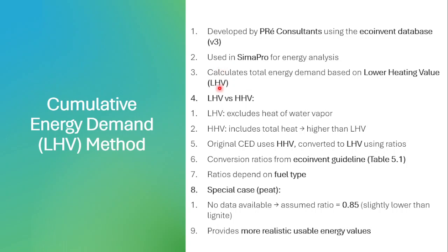This methodology calculates the total energy demand based on the lower heating value, LHV, because as you know, we have one methodology for the CED based on the higher heating value, abbreviated HHV, and the other based on the lower heating value, LHV. The LHV excludes the heat of water vapor, but the HHV includes total heat, higher than the LHV.